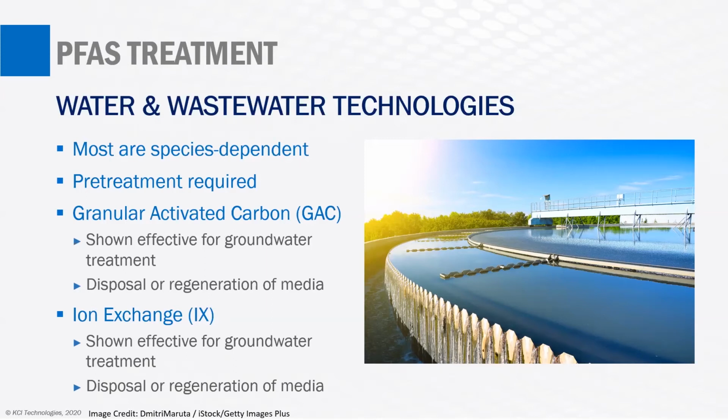Or if we're going to regenerate that media, so we're putting it into a high temperature process to reactivate the granular carbon, or putting it through an acid wash on the ion exchange to release everything that's been attached to it, then you're creating a concentrated stream with PFAS in it that you're going to have to figure out what to do with. So those are some of the unknown questions right now. How are we going to handle that?